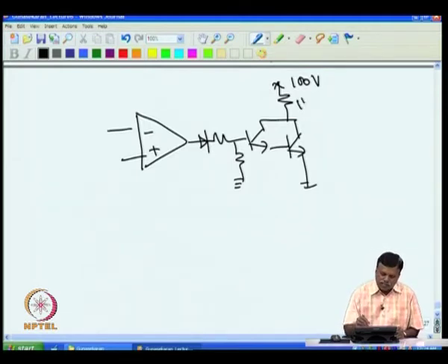In this case, this is the heater. It can be even 5 ampere, because we have put a Darlington, and if you need high power it can go. You can have even a transistor up to 1000 volt, there is no problem, it can apply heater voltage. Of course, you can't use an AC voltage in this case. If it is AC voltage, it is not difficult, you can rectify into DC and give this.